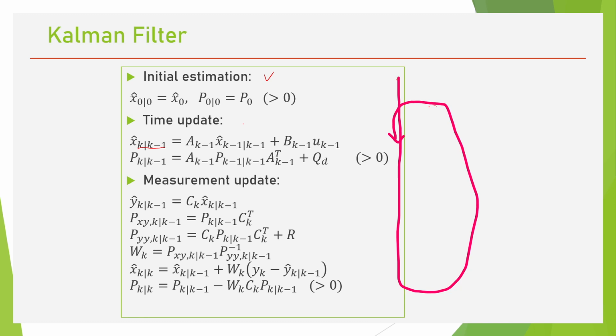But for control of motion, for a motor or something, sample time should be 10 milliseconds or smaller, or maybe 40 milliseconds is fine for a not so high speed robot.